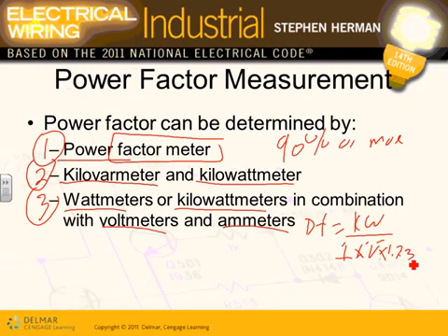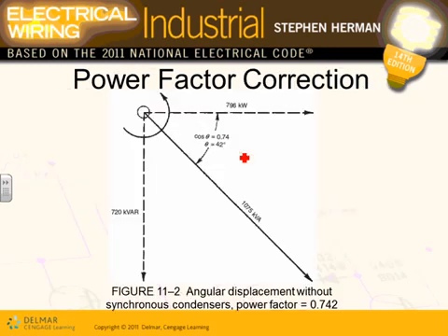So guys, I emphasize that the proper way now to get the power factor is a power factor meter, which is a digital meter that can give you everything. Can I have a thumbs up, Chad? We understand that one? You'll get into all the institutions where they have the kVAR and the kilowatt meter, and a couple of chapters ago we talked about how to read these. The most important thing is you walk into a building and they know what the power factor in their building is. Why? Because if they don't, they'll be penalized.